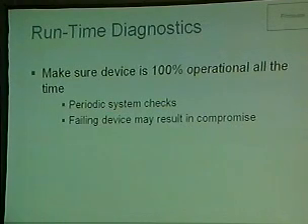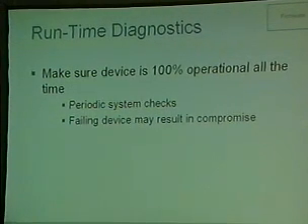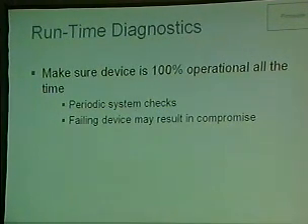So as far as these runtime diagnostics, these are periodic low-level checks. They can be done with the key generation, but it's also just to perform checksums on memory, make sure the firmware, the ROM, and the RAM is consistent and no data has been changed. You get what you expect. A lot of this could be done in hardware, but you can also do some of this in firmware, which is why we mention it in this section.